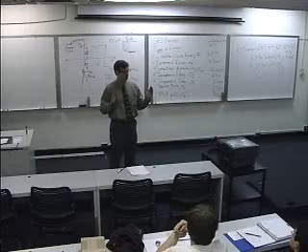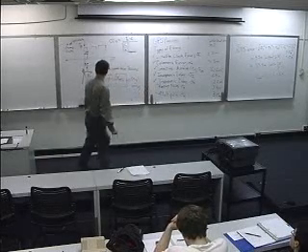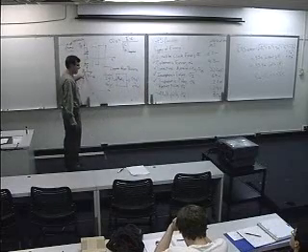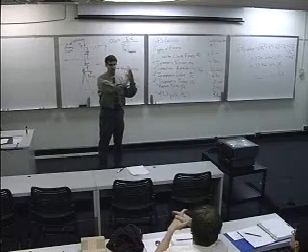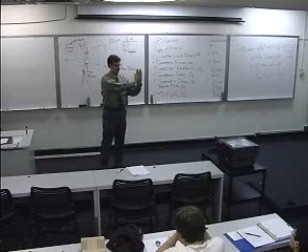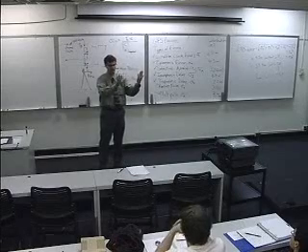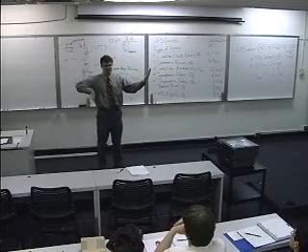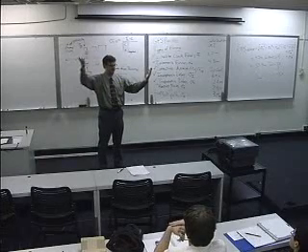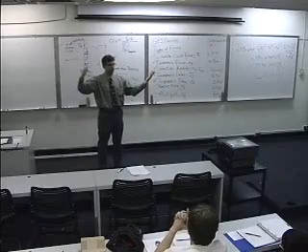But if you want a really accurate measure of when precisely that exact correlation happened, you can correlate over several bits. Try to line up your phases and do a correlation, correlation, correlation, correlation. When you get to the 10th correlation, just keep on going. The phase might flip because a different bit might get sent, but that's no problem. Just keep correlating.